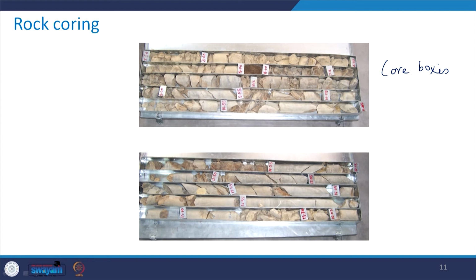Why? I will tell you. These cores are extracted, and during the process of transportation to the lab from the field, there should not be any additional crack introduced. So these need to be preserved properly till we carry out the laboratory tests on the specimen.